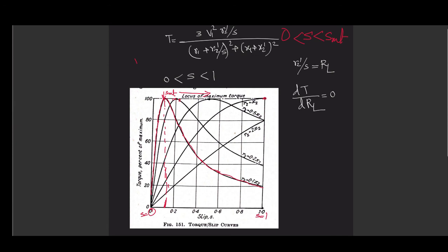Physically, maximum torque is dependent on air gap power, and it is a ratio between air gap power and synchronous speed. Now air gap power and synchronous speed have nothing to do with your rotor resistance. Obviously you can argue that if rotor resistance is small, then it can absorb more air gap power, or instigate flow of more air gap power.